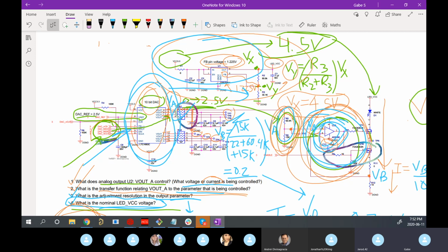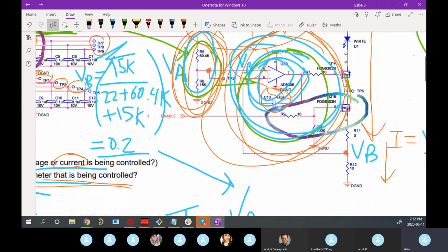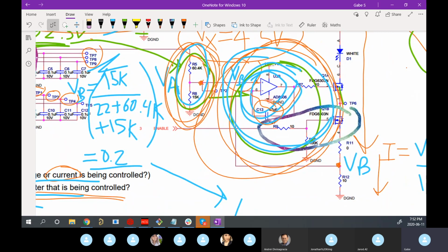Yeah, that's a good question. Like, you know how we said before, what if your resistance of the load is too high, right? And you can't actually control the current to what you need. Do you just measure this pin to make sure what it is? You could. I think that'd be okay. At that point, I think what you would just do is put a current sensor in this path, so that you can validate it that way and get an actual measurement of what you want to control. But maybe a low-cost way to do that would just be measuring this. I don't know if it'd be overkill, because it's not going to hurt you to just shove that into an analog input pin and read it. So yeah, I think that'd be a good idea.